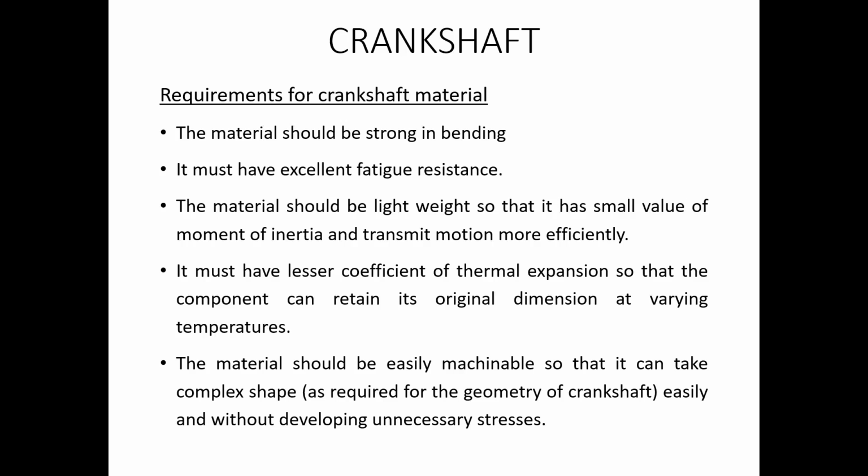So the crankshaft usually experiences very heavy loading. The loading from the forces coming from the piston is transmitted to the crankshaft through the connecting rod, and a lot of stresses are acting on the crankshaft. Therefore, the material used for the crankshaft should be resistant to bending, because a lot of bending forces are acting on the crankshaft.